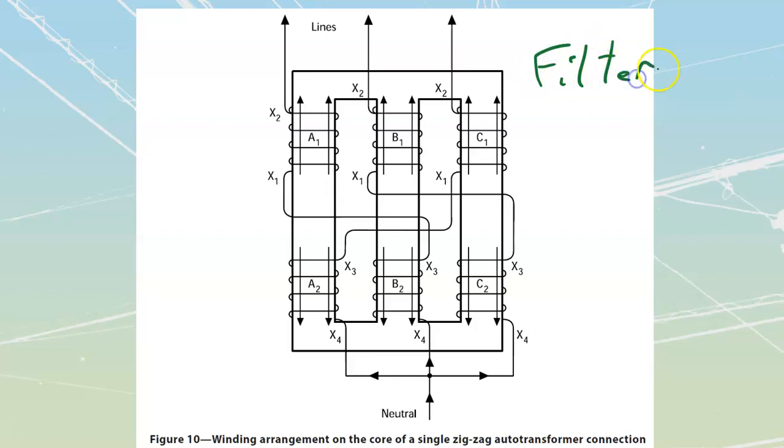It is going to have this neutral connection over here where we're going to take in any unbalanced neutral current. So we get some single phase loads on there. Those single phase loads are going to deliver current in here. And because all 3 of these lines are equal and canceling, it's going to see them all as having an equal value of impedance, and therefore the current is going to split evenly into each one of them.